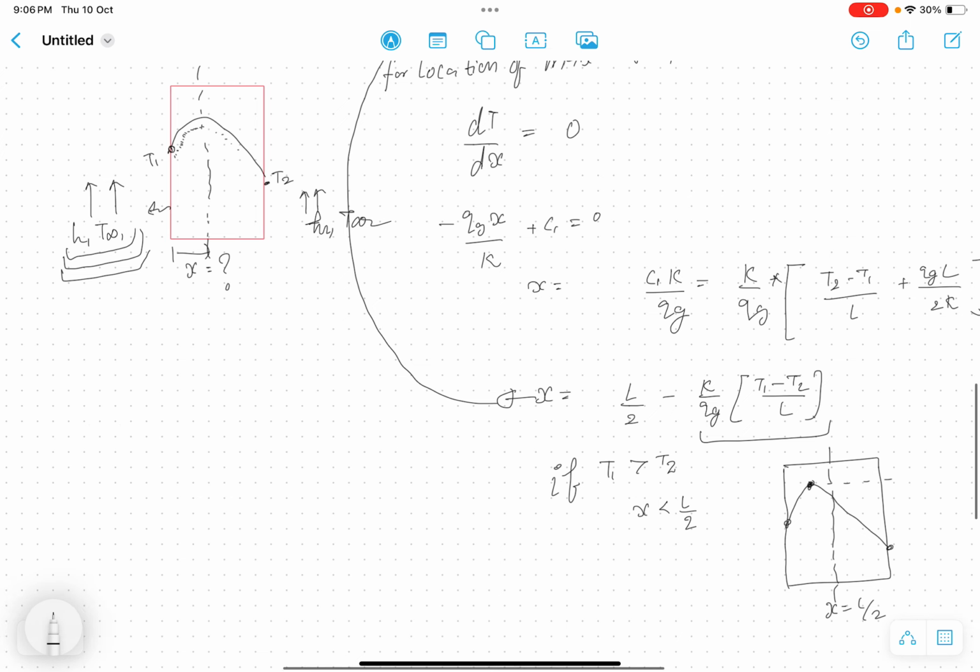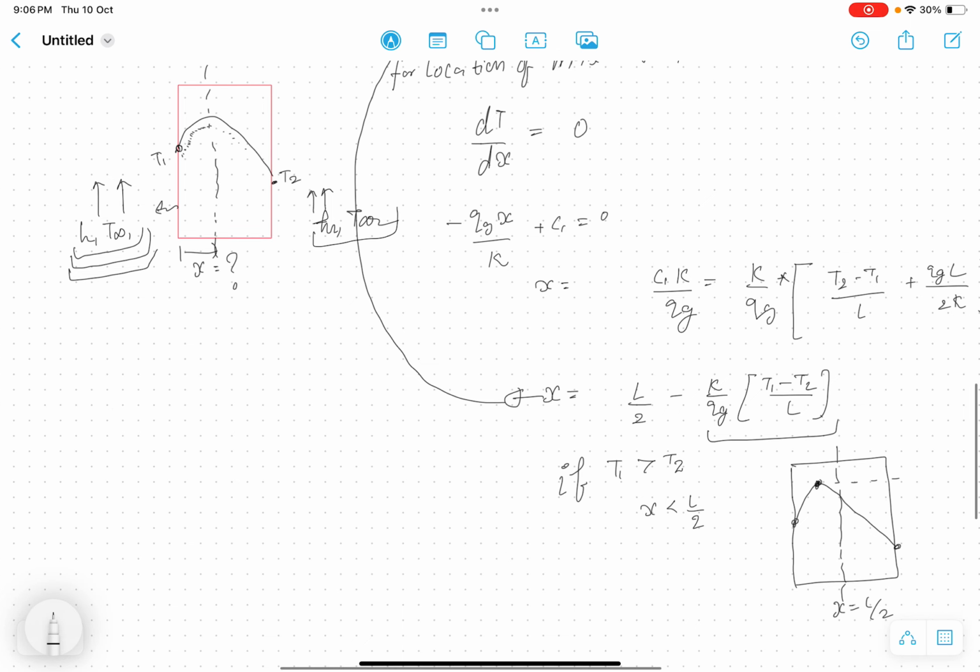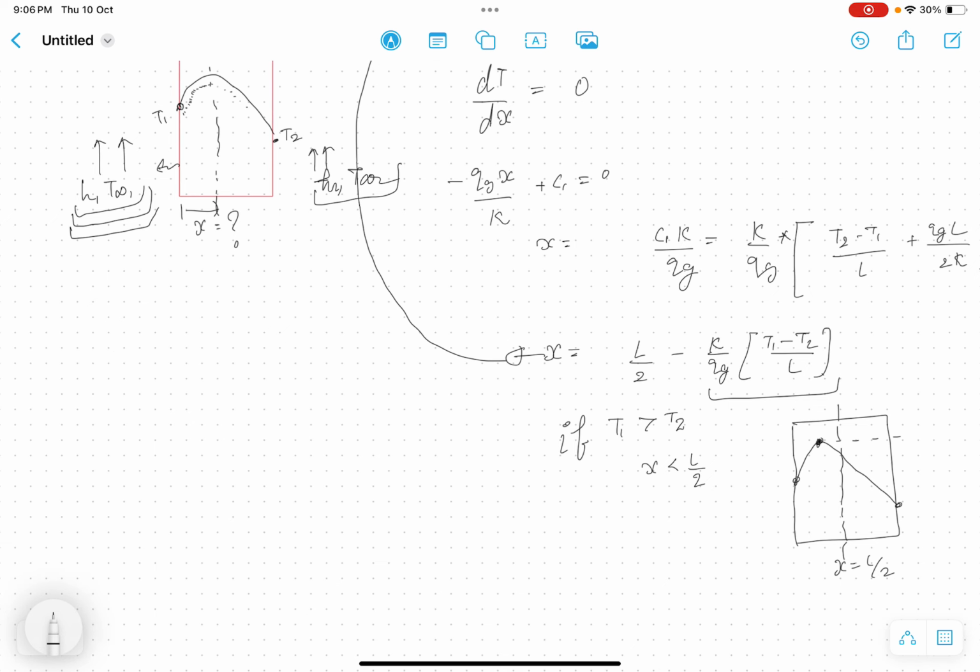That means this side has a higher heat transfer coefficient, meaning higher capability to take away the heat from the right hand side plane. It means the temperature will be lower on that side. Okay, so that is the case. So h1 and h2 are the influencing factors for the values of T1 and T2 on both sides of the plane.